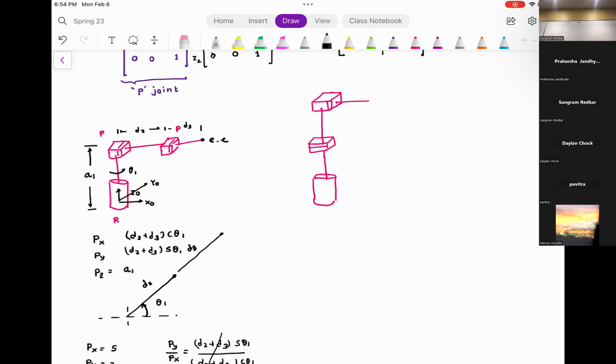MATLAB can use polynomial substitution and solve this more efficiently than we could. And you can't just use tan, because tan will just give you the angle in one quadrant. You have to use arctan, atan2, which gives you the angle in all quadrants. MATLAB does all that, so you use the MATLAB solve function, and it will give you the answer.